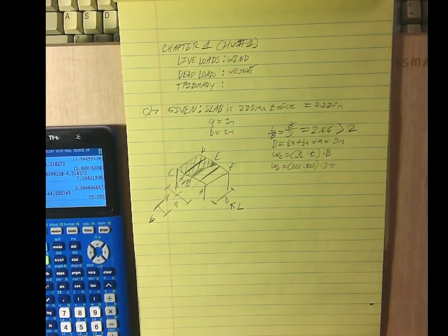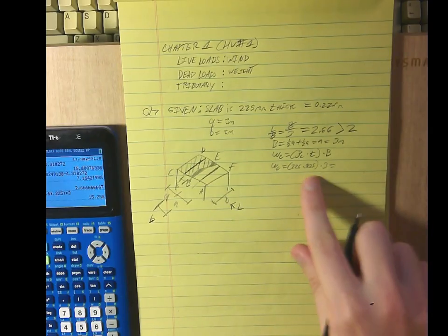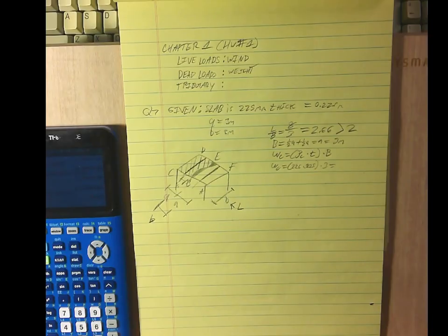Could that be the difference maker? It's 225, I put 225 in. And concrete, we know, is 22.6 kilonewtons per meter cubed. So we should be left with kilonewtons. This is going to be meters squared. So it should be kilonewtons per meter.